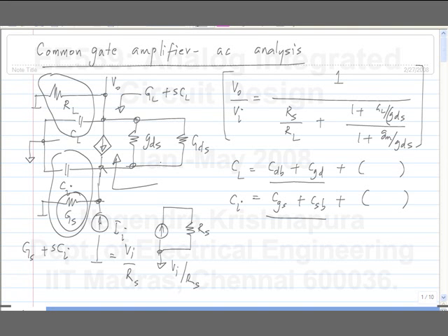You will not introduce an additional pole because if you look at the 3 voltages, just like in the common source amplifier, only 2 of them are independent. In the common source amplifier also you have this network of capacitors, CI, CL and a capacitance across the gate source, gate drain. So in this case it will be across drain source. What it will do is it will introduce a 0. So it will still be a 2-pole system, but it will introduce a 0.